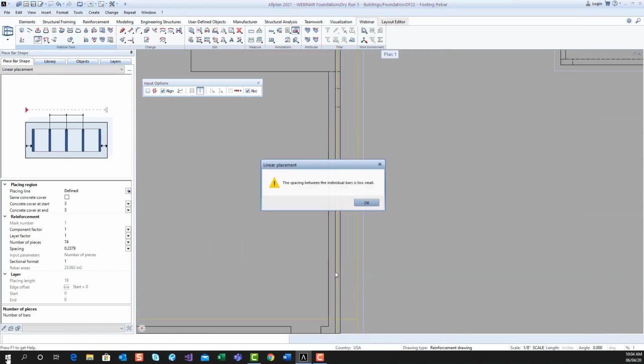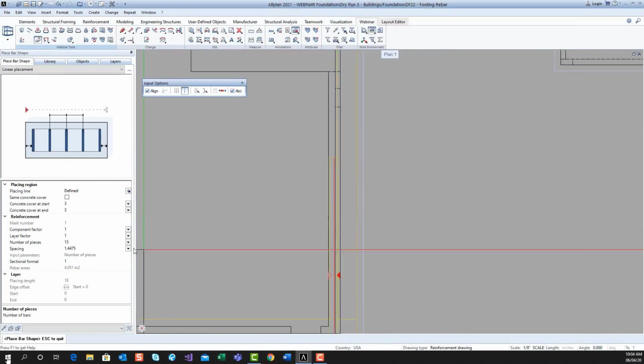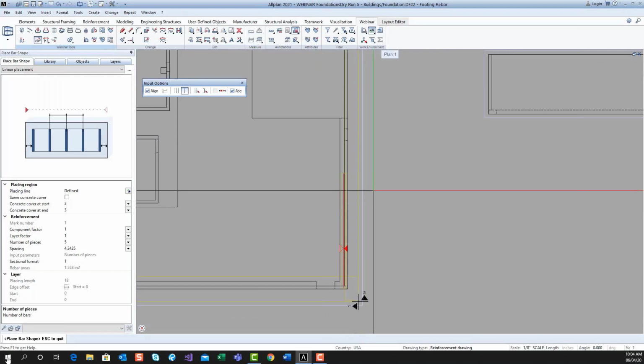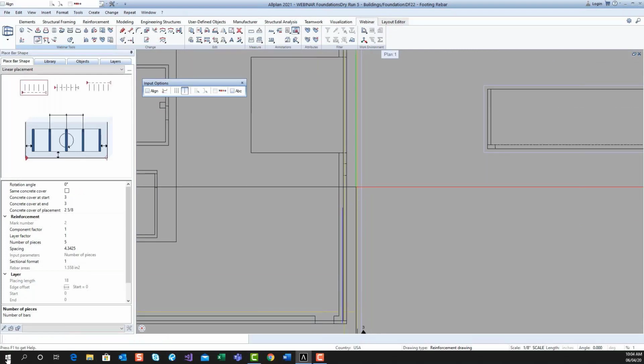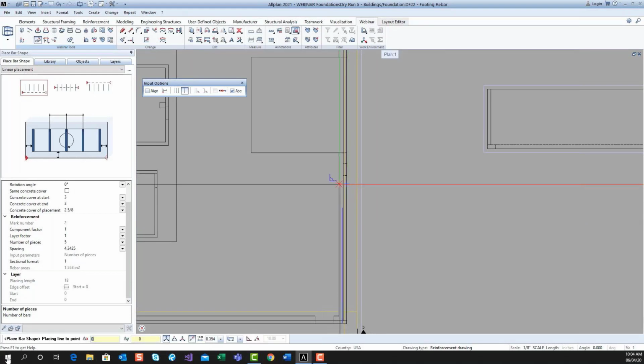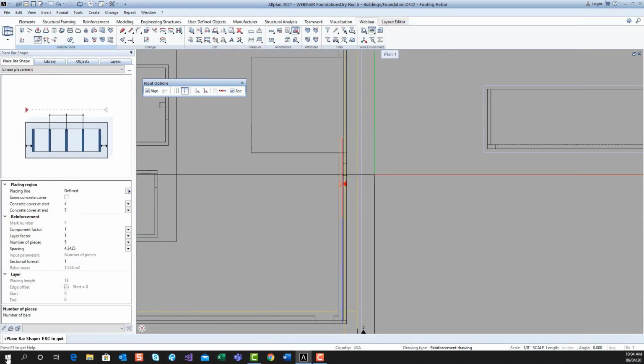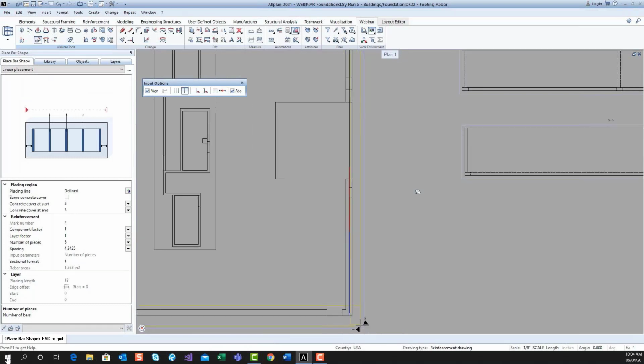By having the align button clicked off, it knows where to throw it into the model in my plan view. That's not my 3D model, that's my plan view. I'll change the number of pieces to 5. You'll notice that after I put these in, the labels on my other elevation have changed to show the proper number. Instead of 0, they now say there are 5 pieces.